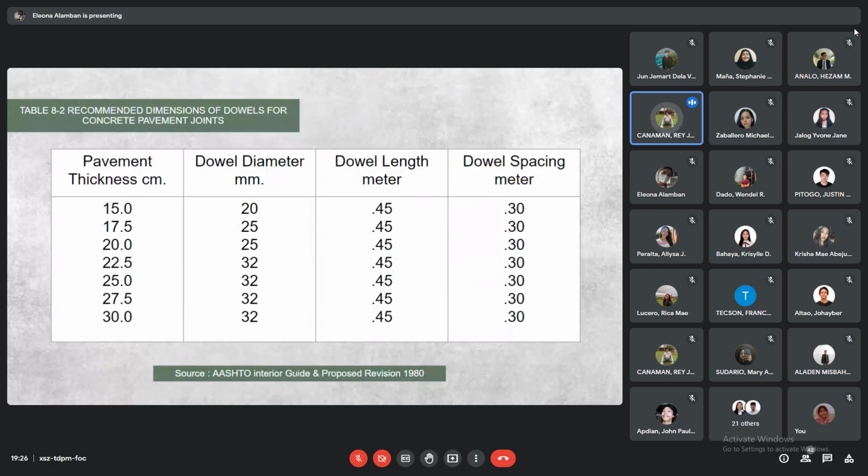A concrete expansion joint, or what we also call a control joint, is a gap that allows the concrete to expand and contract as the temperature changes. It forms a break between the concrete and other parts of the structures to allow movement without causing stress, which can lead to cracking. There are many reasons expansion joints are required, such as structure size or length, structure shape or irregularities, the isolation of dissimilar building classifications, sometimes fire separation, and lastly thermal movement.